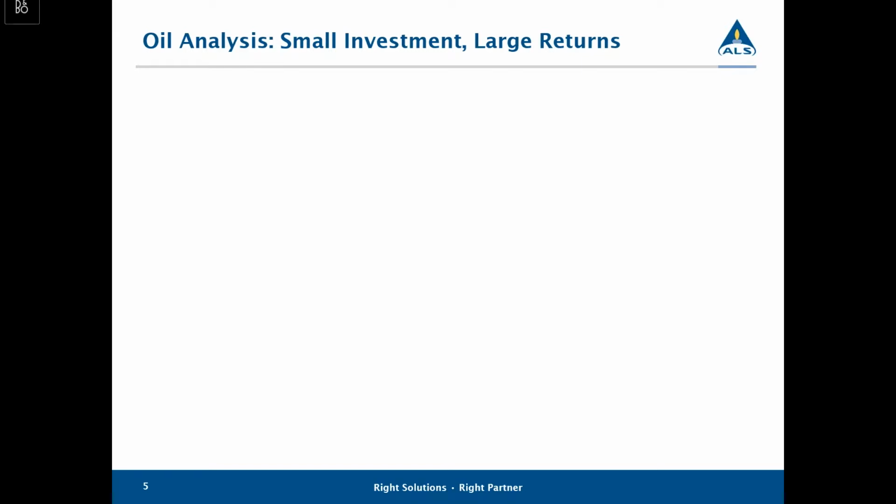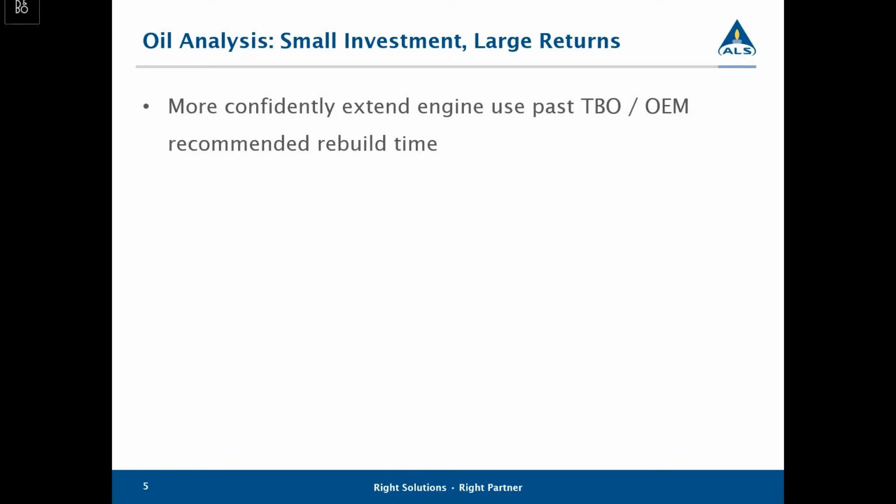So we look at oil analysis as a small investment, but you get a large return. For those that are extending engines past their TBO, you can more confidently do that. I don't fly an aircraft personally, but I have a personal vehicle that has a lot of miles on it. And through doing oil analysis, I'm very confident that the engine in that vehicle is going to have a lot of extra life in it, where one might be concerned about how much longer it might last. I at least have confidence of that, and I know that aircraft owners are the same.